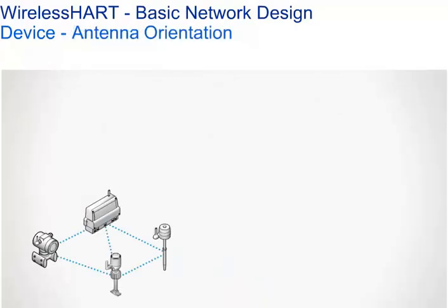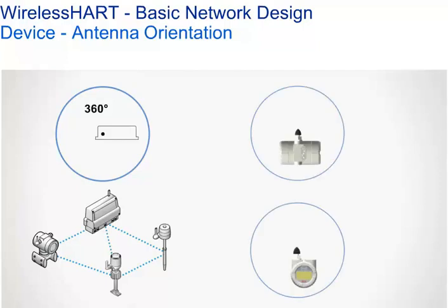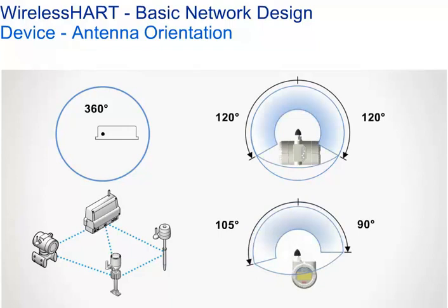The WirelessHART gateway antenna spreads the signal in all directions. The antennas of our WirelessHART transmitters also do this, but the housing can seriously affect the signal. ABB devices feature directional antennas, such that they point at the gateway or at the next device in line of sight. This is a plus, considering all the possible obstacles at a plant.